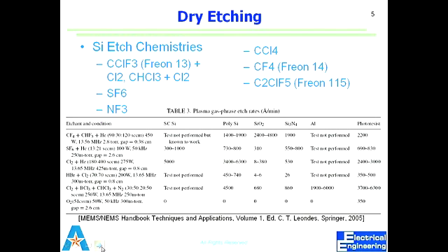So the question is, would it etch and get inside between the photoresist and silicon dioxide? Would it? Those who are here from the second slide onward, would it? Remember, it depends on the anisotropy of the etchant. No, what was the dry etching process? What is the first step in that chamber? You apply a bias, right? The bias gives directionality to the ions.